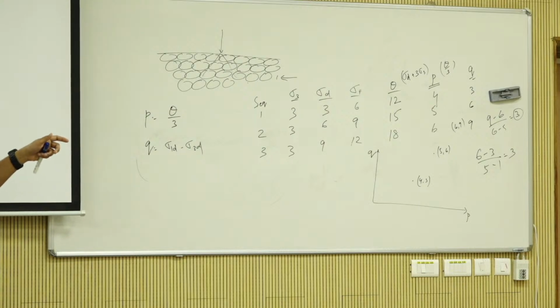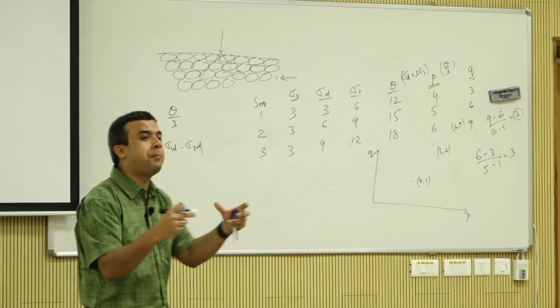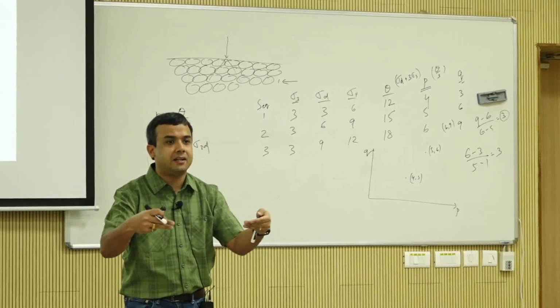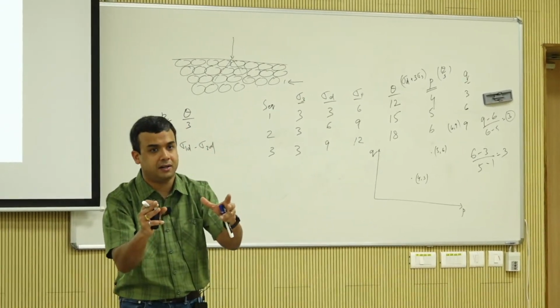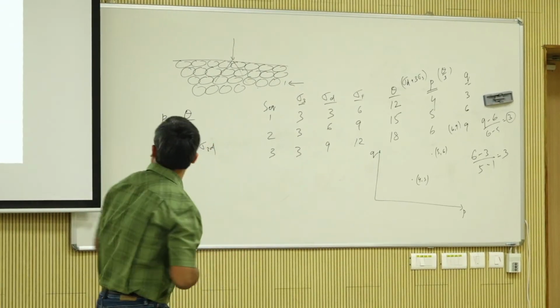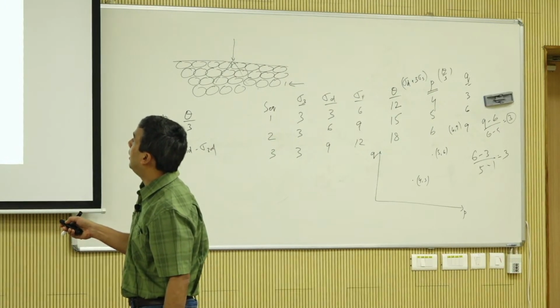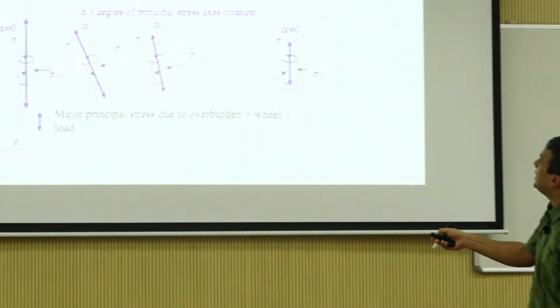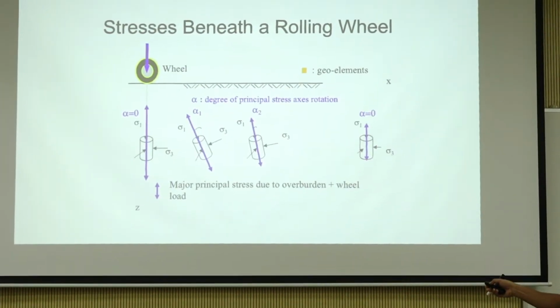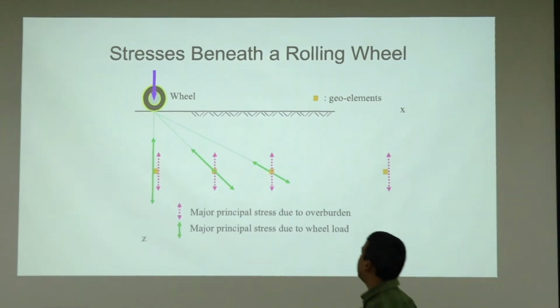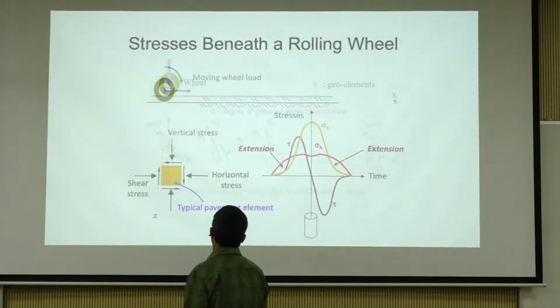Okay. So what is horizontal? Horizontal pulsing is the extreme case, right? This is one case. This is completely another case when the stress path has completely rotated. But as you know, in these plots over here, you see that it gradually rotates, right? If you do that, it basically gradually rotates as the soil moves.